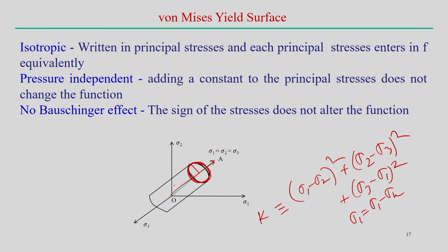This is the original state of stress, and we can see that when yielding occurs, the actual state of stress consists of both the deviatoric and the hydrostatic components, but the hydrostatic component does not alter the yield functional form.